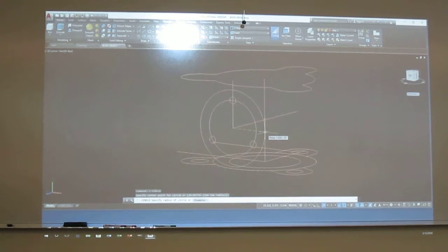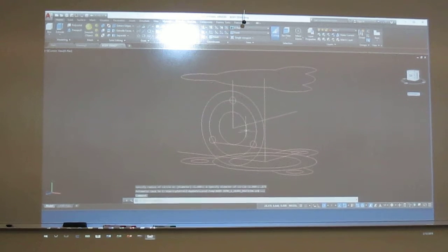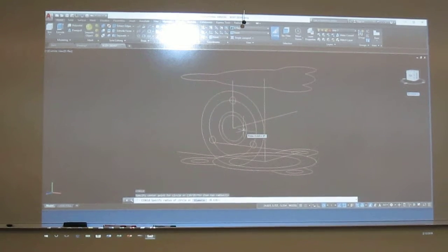And let's see, the first big one is what? Diameter 2, so that's got a radius of 1. And then I move to the inside. The next one, we're skipping, yeah. So what is it, 0.875? So D, enter, 0.875, enter. And then the last one, D, enter, 0.562.